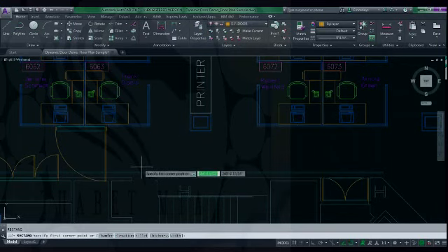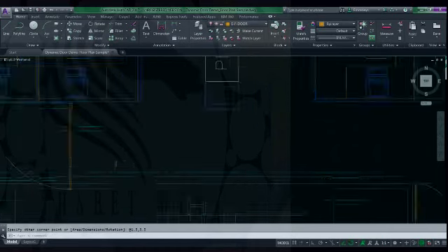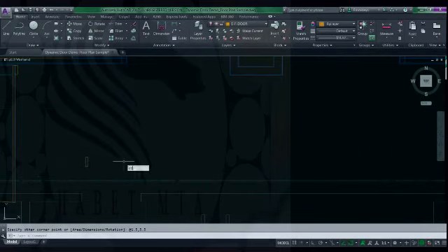So I'm going to go ahead and make my door jambs. And let me select my point. I'm going to go ahead and make my door jamb 1. Let's zoom into that. And I want to copy that. I'm going to go ahead and put my ortho on as well. Pick it there.